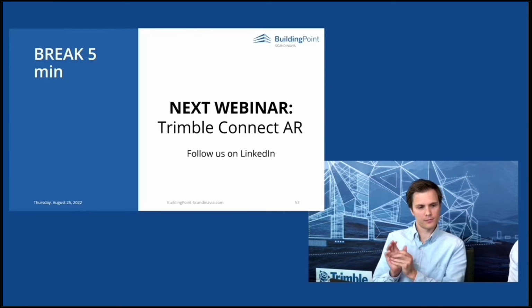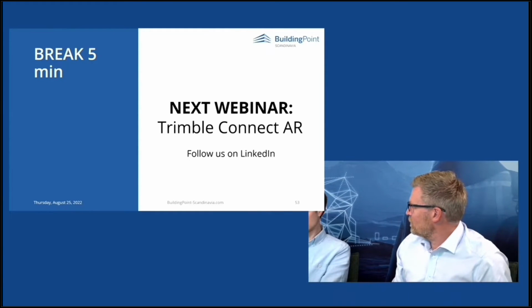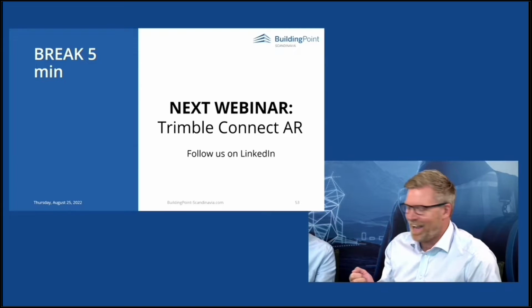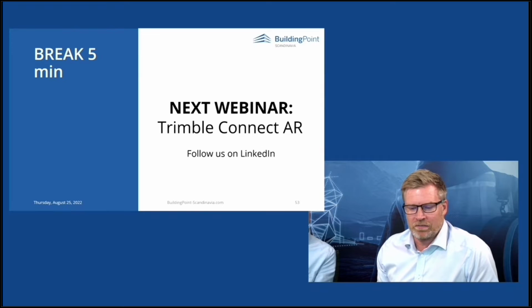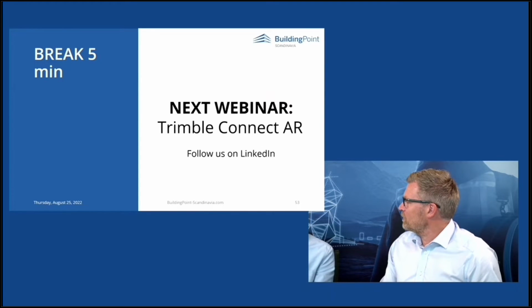First of all, Ole Christian Eishammer from Trimble in Sandvika just mentioned a tip that is really crucial. We forgot to mention that. If you are the administrator for a project and you leave the project without assigning someone else, then the project is without an administrator. I think Trimble Connect will help you avoid that. It would be weird for Trimble Connect to have a project without admins, but it is more practical to decide it before than to do it afterwards. You will get a warning.